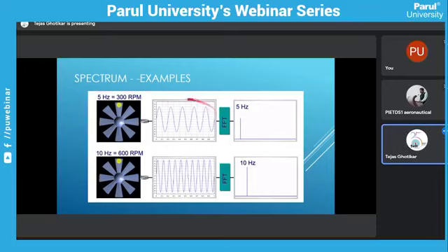Okay, they want to look for this type of graph, but what they will have is in the frequency domain. It will be a frequency curve. It means at 5 hertz or 10 hertz, what is the amplitude? Because it's a cycle, it is continuously going over. So what is the amplitude at 10 hertz? This is the amplitude, right? It's 6.5 or something. So that is the magnitude we have here at 10 hertz.